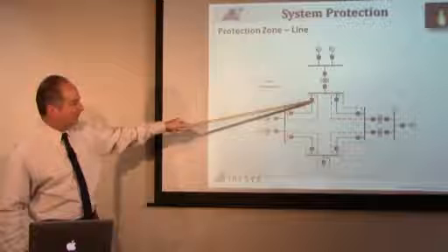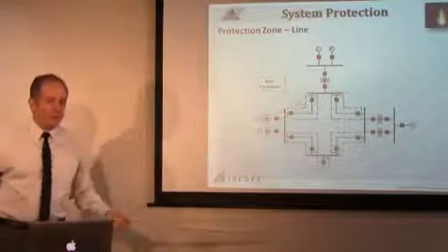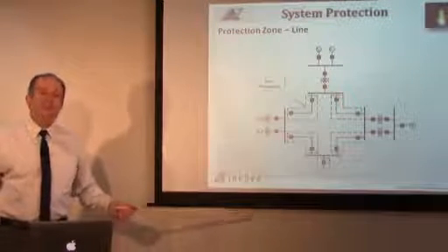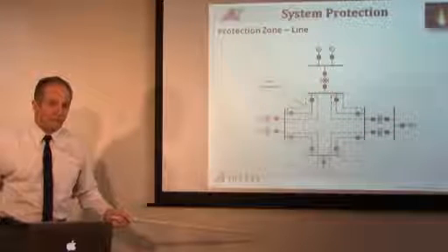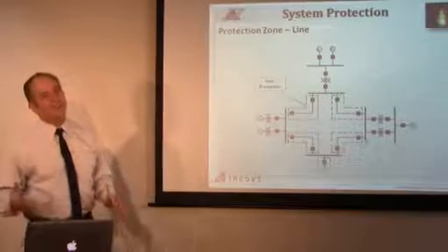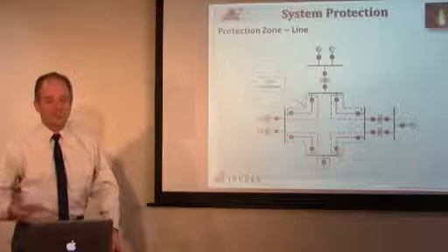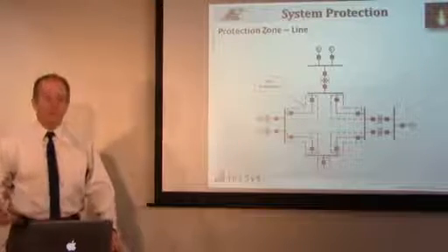And the reason for that is there's multiple. If that breaker doesn't trip the line, the current in the CT doesn't go to zero. So if the current in the CT on that breaker doesn't go to zero when that breaker is supposed to trip, that means there could be a breaker failure condition.